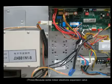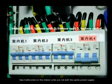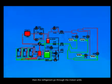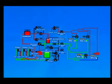3. Some indoor electronic expansion valve has a malfunction, or the indoor units are not on the same power supply and some indoor units are powered off. Then the refrigerant goes through the indoor units which are powered off or whose electronic expansion valve is stuck. It affects the system running performance.